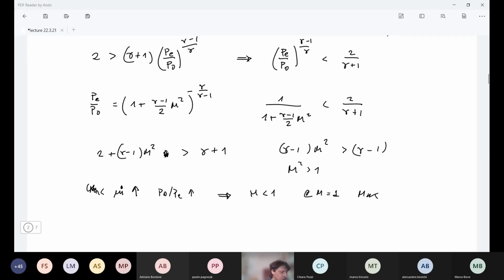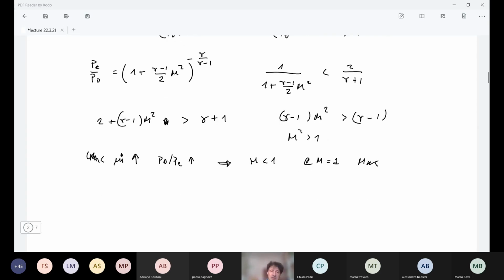So this corresponds also to our understanding that at this point we no longer have the possibility to inform in a way what is ahead of our exit section of further decrease of the ambient pressure. So this is what happens when we have choking. We have no longer information going from downstream towards the upstream flow condition.